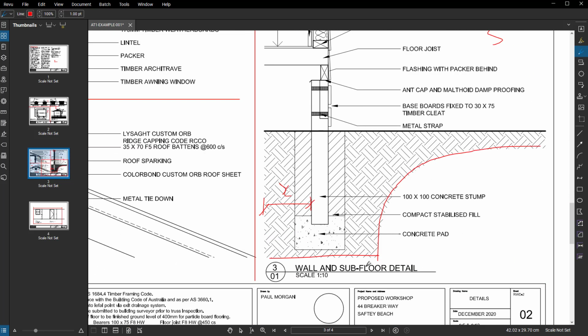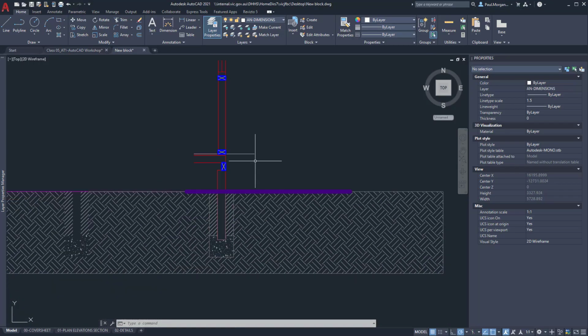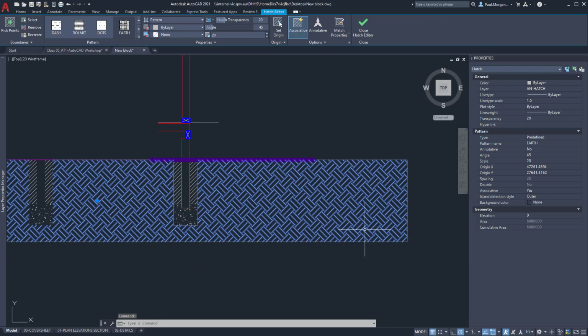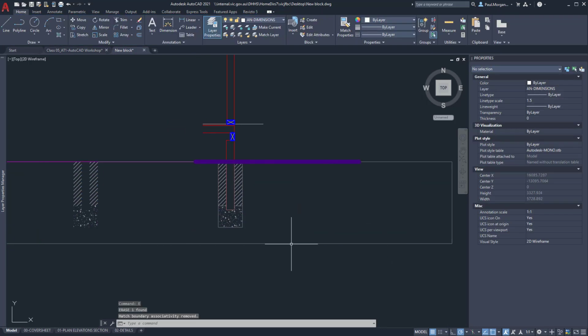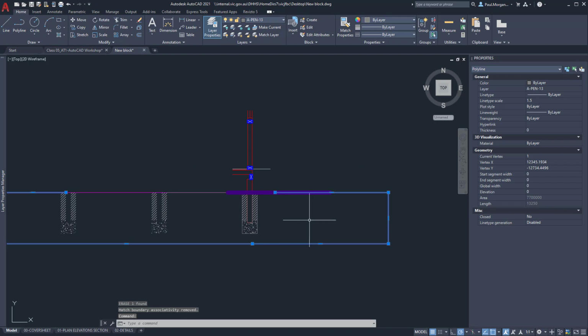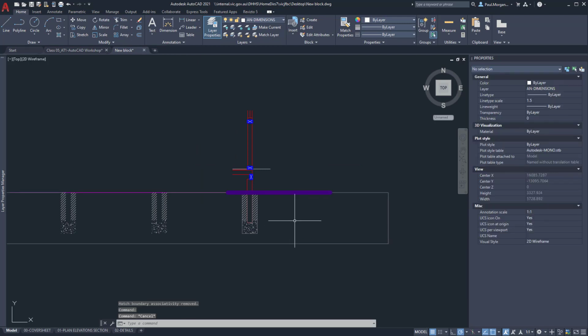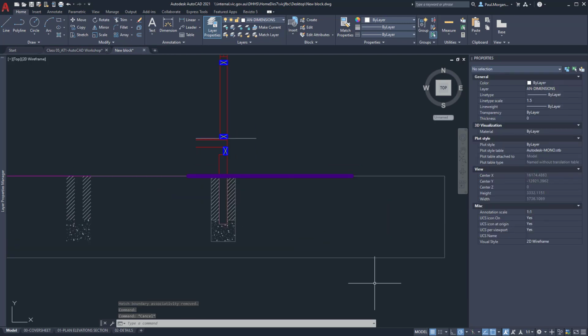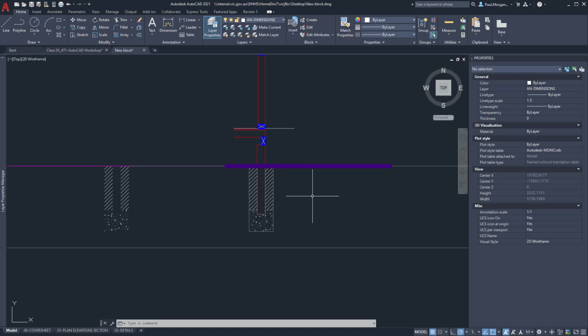So the hatching, for starters, was deleted and then redrawn and rescaled and just carved a little bit differently to give a bit of a different view. Plus, the other thing it does is it means that you have your writing here that's not impacted with the hatching zone. That's actually much easier than it seems. I'm going to delete that. I've still got my original zone that I use as my bounding box of my hatching.